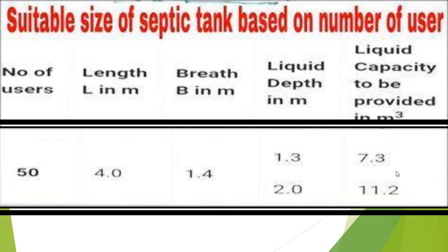So now, introduction and process of the septic tank. A septic tank is a rectangular chamber generally constructed below the ground as a primary sedimentation tank to carry the disposal of night soil for a long time, that is 12 hours to 36 hours, as compared to an ordinary sedimentation tank which carries it for less than 2 hours. A septic tank is constructed either with a concrete or brick wall containing two or more chambers. This is mostly used in rural and urban areas where there is no proper management of the sewer system, that is the drainage system.